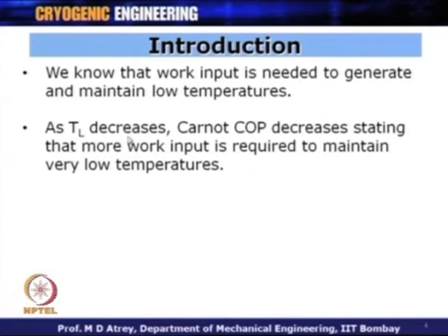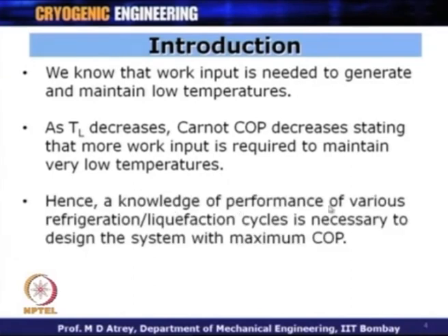If you remember the last lecture, we talked about watt of power input per watt of refrigeration, and we found that the watt of power required per watt of cooling effect increases as we go to lower and lower temperatures. If you want to reach lower and lower temperature, your work input increases. Hence, a knowledge of the performance of various refrigeration and liquefaction cycles is necessary to design the system with maximum COP. Ultimately, the important thing is to have maximum COP or maximum efficiency, and therefore one has to understand what cycle one should use in order to reach a particular temperature or to liquefy a particular gas.